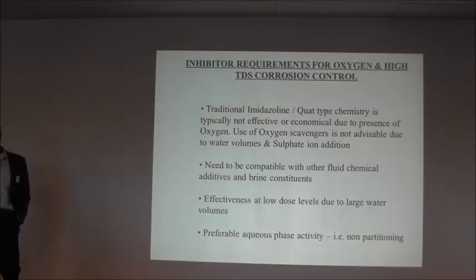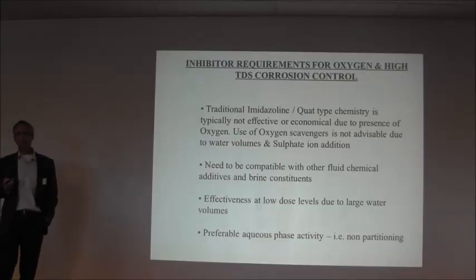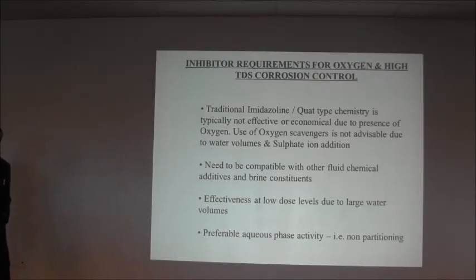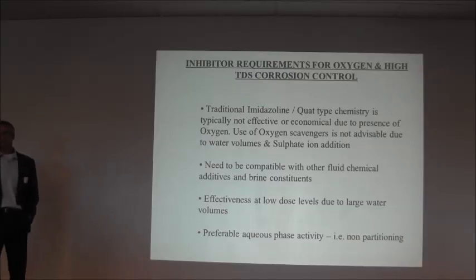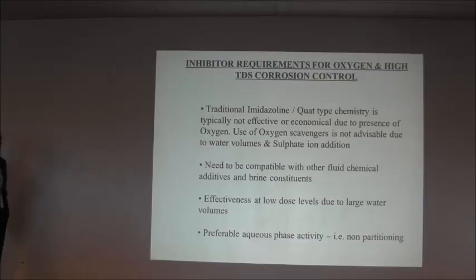Again, with high salinity fluids, a lot of times those waters of hydration are used to keep the other ions in solution, the sodiums, the chlorides, whatever calcium, barium, strontium, sulfates, etc. may already be there. And so to put other chemistry into that solution, you need free waters of hydration that can solvate your inhibitor. And a lot of times calcium again can be an issue. You can form calcium salts of various inhibitors.